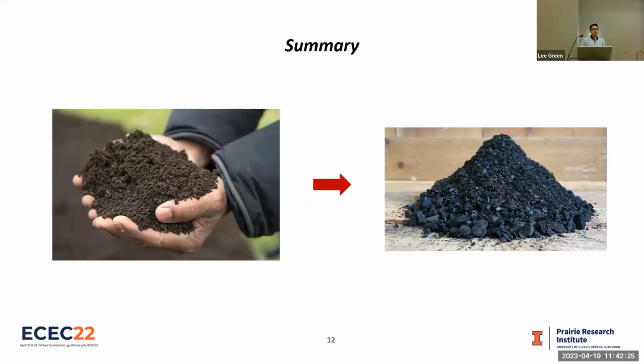So in summary, wastewater treatment plants have a good product in the biosolids. However, it needs to be treated before a safe land application. A cost-effective way that we are proposing is to create biochar from those biosolids. And as I said, we are not destroying the PFAS, but we are encapsulating and trapping the PFAS in the char. We are carbonizing the microplastics as well, and we are killing all pathogens. At the same time, we preserve the nutrients and minerals, so it can also be sold as a soil amendment.